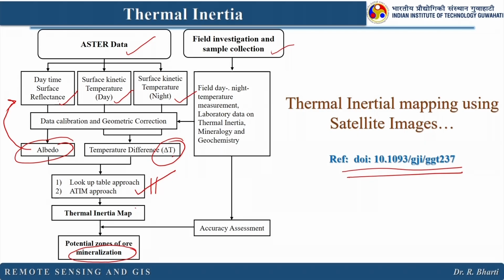Once we have this satellite-based thermal inertia mapping, at the same time we also conducted field day and night temperature measurements and laboratory measurements of thermal inertia. We calculated the thermal inertia of selected materials which we collected in the field, and we also estimated the mineral composition using conventional techniques like XRD, XRF and ICP.